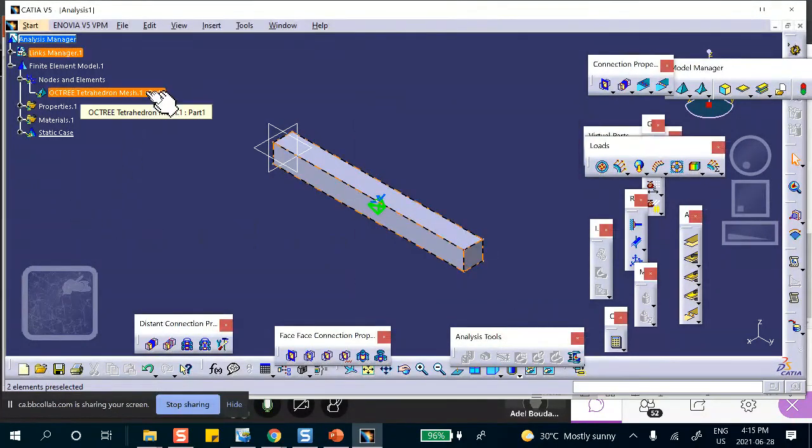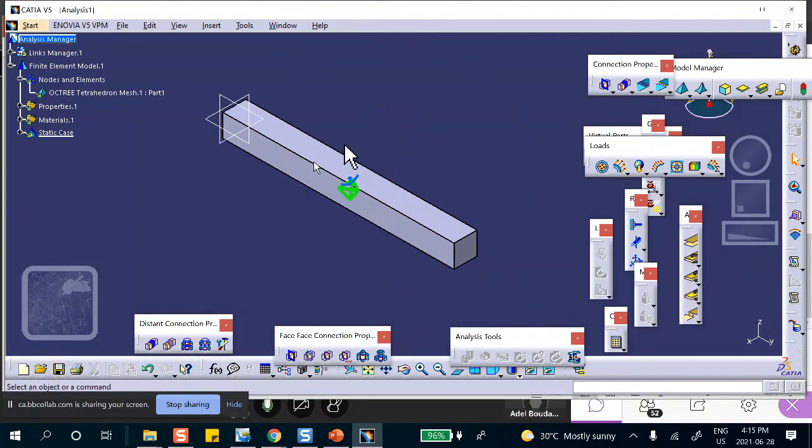You just go ahead and do the linear one, okay? And even for the linear, don't put a micron for the size of this object, because there's going to be a million elements there. You're going to sit there forever in order to finish the problem. Okay, I'll keep this. Now, obviously, the bigger it is, the less accurate the results, the less accurate the frequency, etc. All right. Now, let's save the analysis.